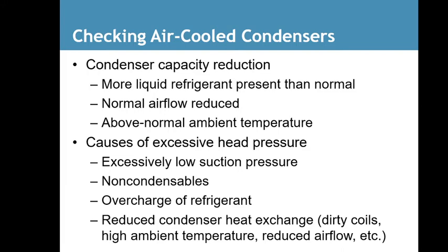Non-combustibles. Overcharged refrigerant. Reduced condenser heat exchange. Dirty coils. High ambient temperature. Reduced airflow.